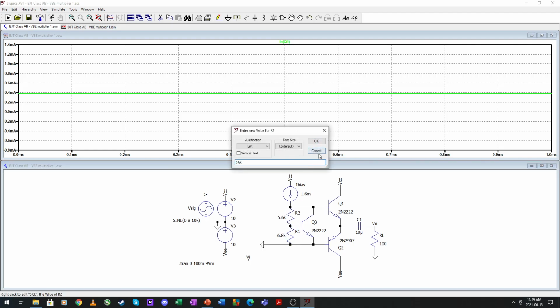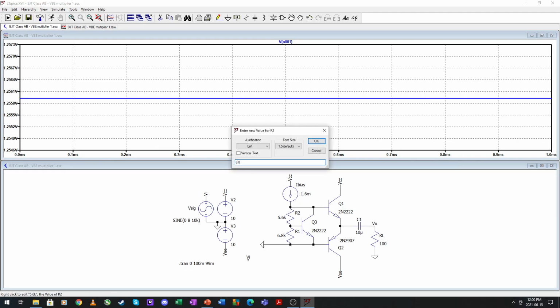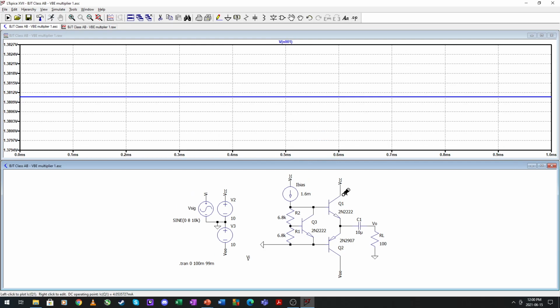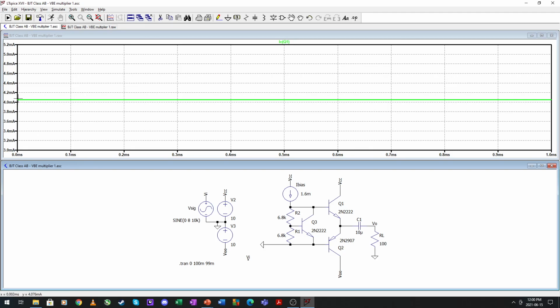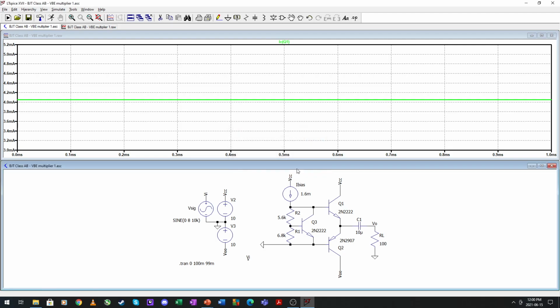So we check here, we have 1.255 volts. So 6.8 Ks, that takes us to 1.3, so that will move upwards again. So this resistor right here is very sensitive, and you'll find that this is sometimes just a variable resistor, so that you can tune your quiescent current to whatever you want it to be.